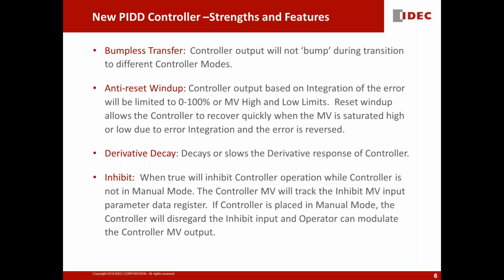The anti-reset windup is when the controller, based on the integration of the error, is always limited to 0 to 100%. So it does not wind into uncharted territory. It's always going from 0 to 100% to limit any winding and stuff like that.